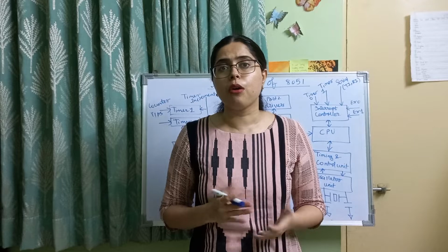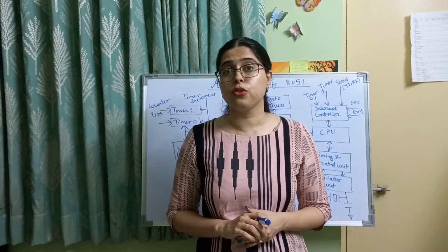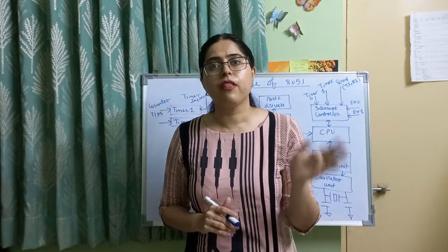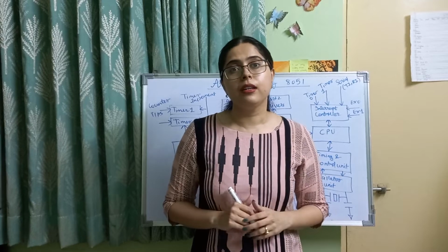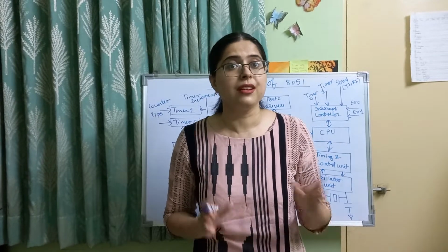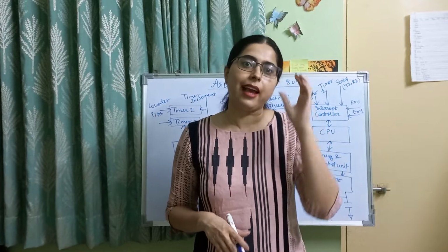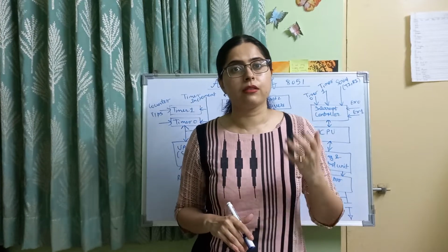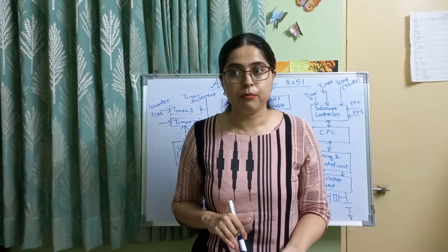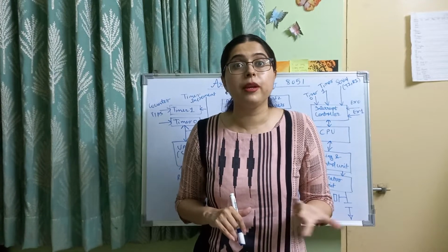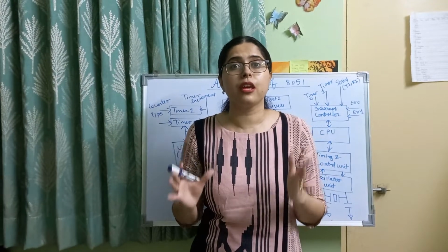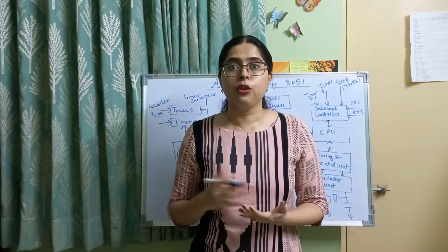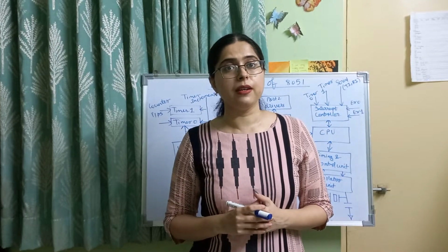Now where is the result of these operations performed by the Boolean processor stored? There is one carry flag inside the 8051 microcontroller. Where is the carry flag, and what is the function of the carry flag? We will discuss that under the section registers in 8051. Currently you just remember there is one carry flag inside the 8051 microcontroller, and the results of these operations, that is bit set, bit clear, complement bit, bitwise OR, bitwise AND, the results of all the bit manipulation operations are stored in the carry flag. The carry flag acts as an accumulator in your Boolean processor. Okay, clear till here? Fine.